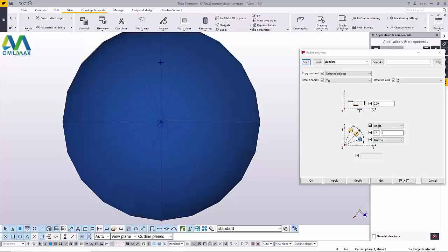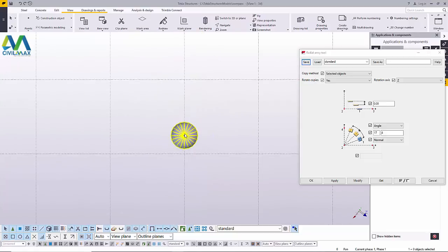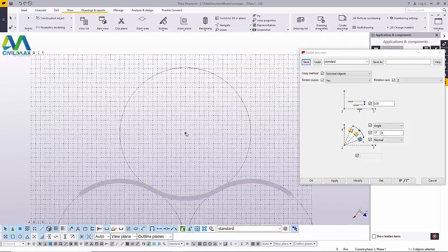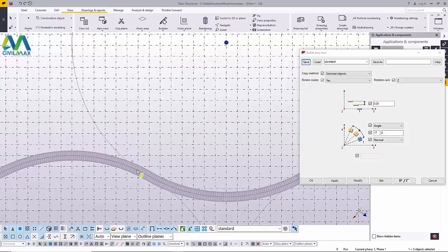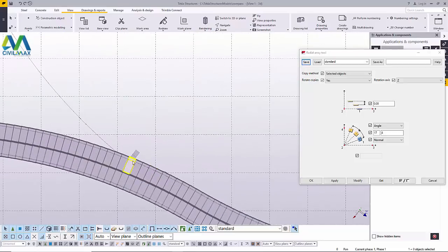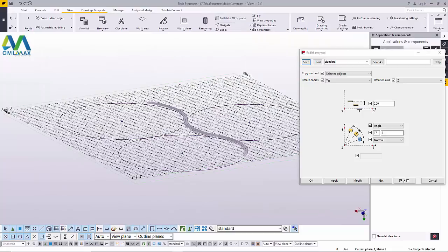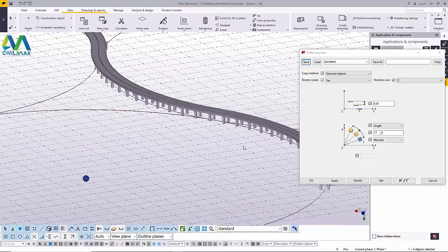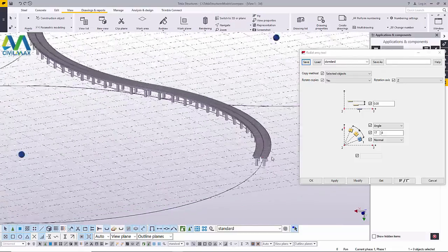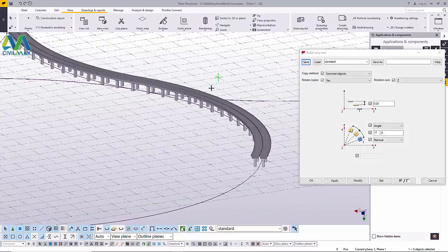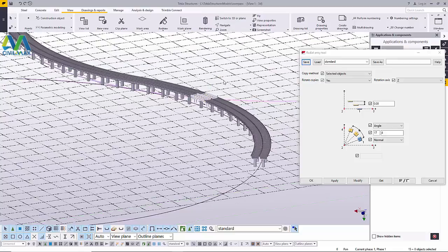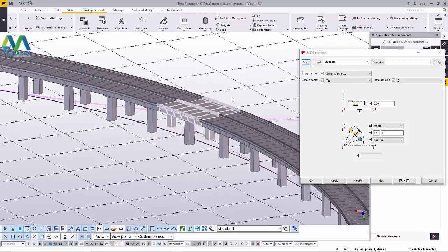Then press your middle button on the mouse and zoom out and check whether what you've just done is following the directions you really prefer to be followed. Now I can see one is protruding, and we want to switch back to isometric view and check that and correct, and check whether we really need it or we can do away with it.